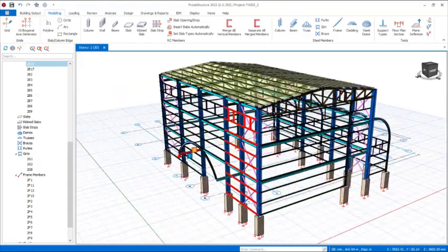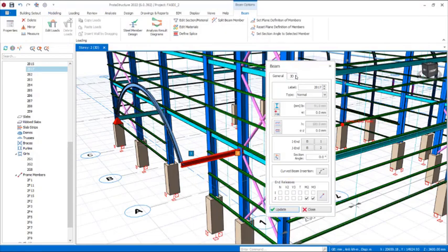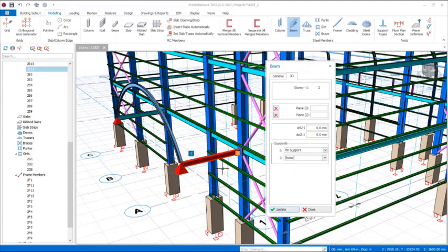Come over to this other side, select this, also the property of it, and then we go to the 3D tab right there, I end as well. Click on the pin support, click on update to have this. So we have actually supported this with a pin support which resists the vertical and horizontal forces and not movement. It is only the fixed support, the support at the foundations, that resists both vertical forces, horizontal forces, as well as movement. So click on update and then close options.